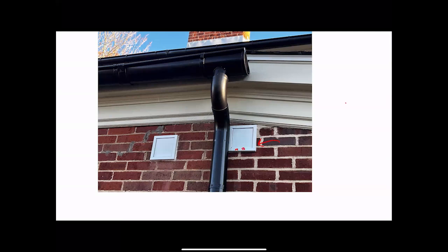And so the way it works is here's the house, here's the duct going to the powder room in section. And then there's like a damper. In this case, the damper is on a hinge, and the hinge has a little magnet there, and it continues down. And when there's airflow pushing it, what's supposed to happen is it's supposed to fly open a little bit from the positive pressure on the windward side, on the upstream side of the damper, relative to the negative pressure on the downstream side.